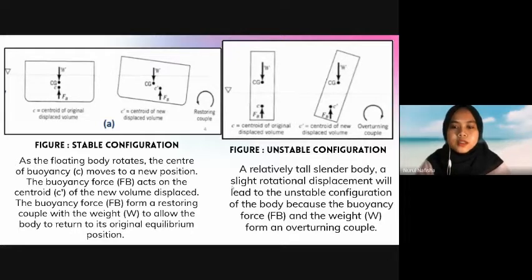The buoyancy force, the FB, will then act on the centroid of the new volume displaced, and thus the buoyancy force FB form a restoring couple with the weight of the body as they are equal in magnitude and opposite in direction. Hence, the floating body will return to its original equilibrium position.